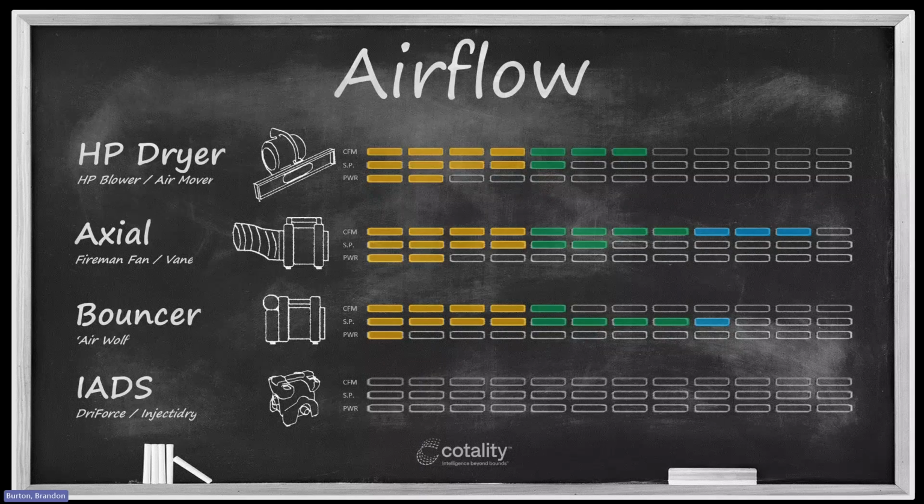So just think about the power of 7 inches of static pressure for a moment, and then think about taking that off of a castle, right? And instead plugging it into a wall cavity, right? The amount of static pressure there is high enough that either air is going to move through that cavity or the cavity is going to inflate. Both are entirely possible, by the way. All right, so that's what 7 inches of static pressure can do for you.